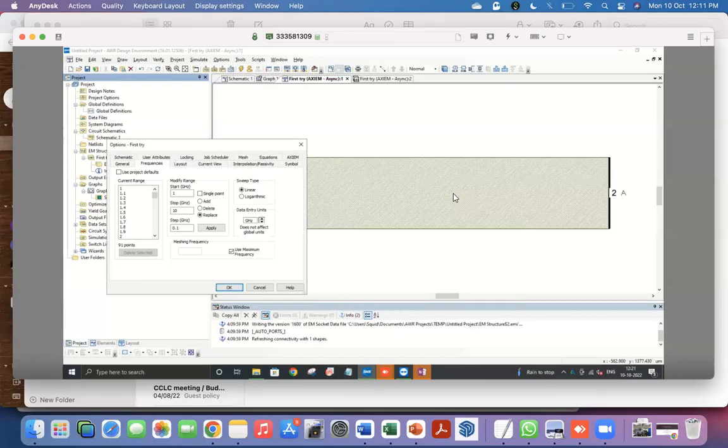But it's in this kind of situation where you have two different sets of things running, because simulating simple inductors and capacitors in a circuit is instantaneous for all practical purposes. EM simulation can take seconds to minutes to hours. So what Microwave Office does by default is that, let's say your frequency range of interest is between 4 and 5 gigahertz.